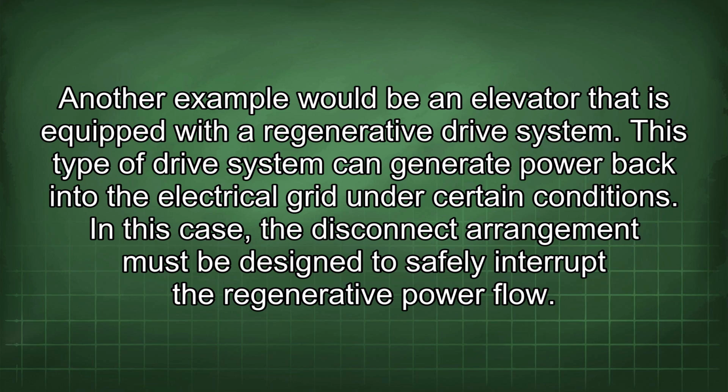Another example would be an elevator that is equipped with a regenerative drive system. This type of drive system can generate power back into the electrical grid under certain conditions. In this case, the disconnect arrangement must be designed to safely interrupt the regenerative power flow.